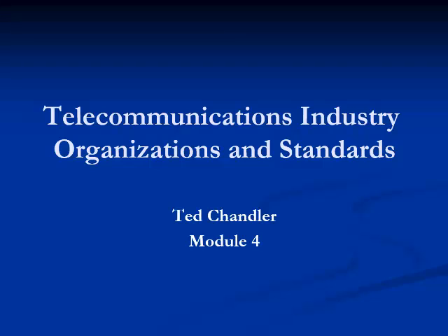In July of 1991, the first version of the telecommunications standard was published as ANSI/EIA/TIA 568. The 568 standard was revised to 568A in 1995, and in 2001, 568B.1, which is the basic or general part of the standard, B.2 for copper cabling, and B.3 for optical fiber cabling were published. Along with this mother standard, other standards evolved over the next 15 or 20-year period.